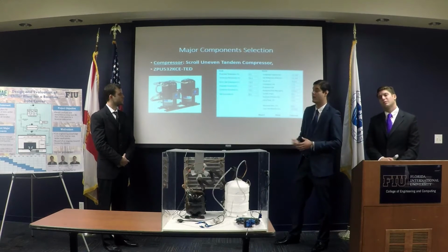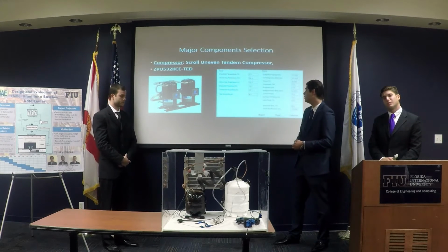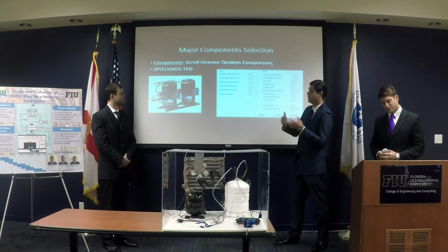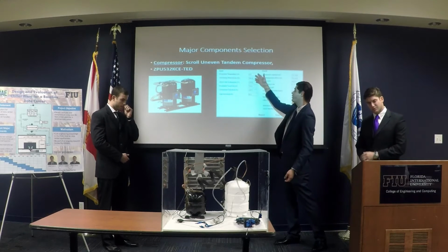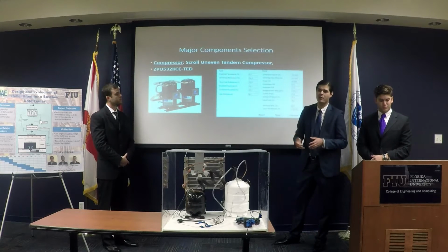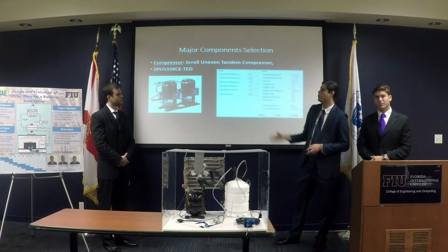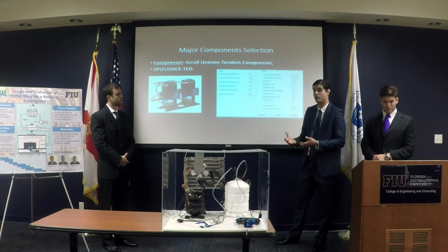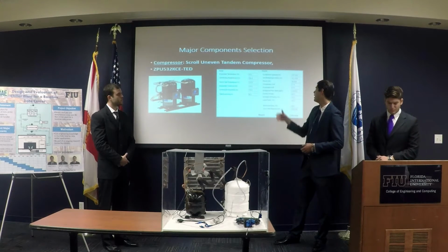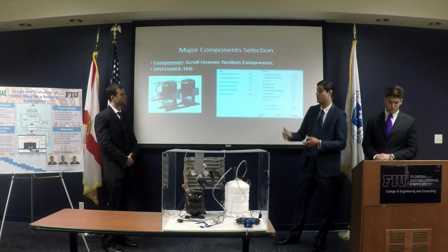This is manufactured by Copeland. We use the software selection tool from the company. Again, taking into account the design operating conditions given here, the software gave us at least 21 different compressors, but only this part number, this compressor, was able to provide enough cooling above 120 kilowatts. That's why it is used. The other ones were below.